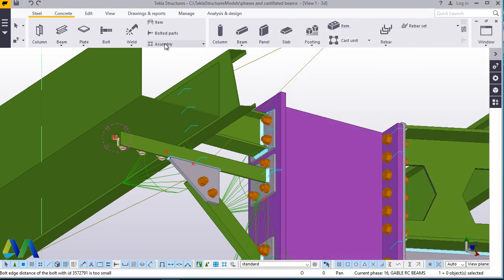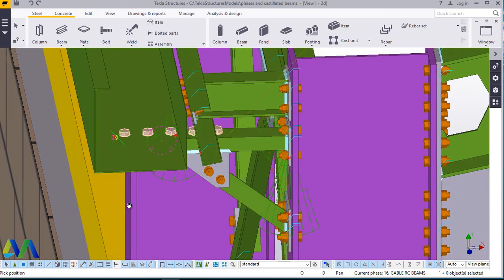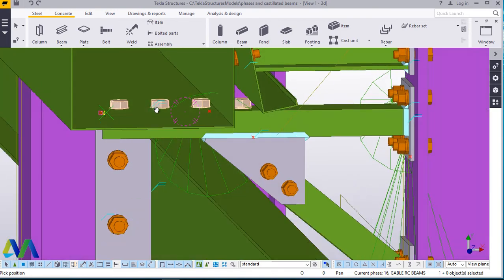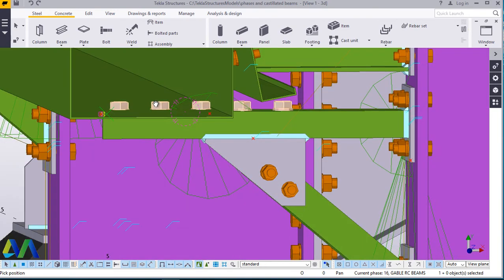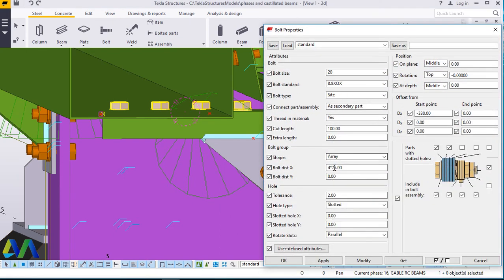Press Ctrl R, then you pick your rotation spot just to help you turn this round, and you realize that 4 are too many bolts to apply here. Just double click on that. After double clicking here, you only need 2 right there. Click modify.